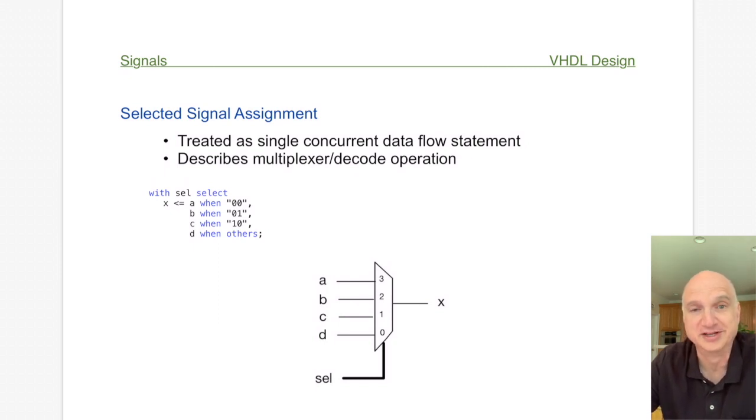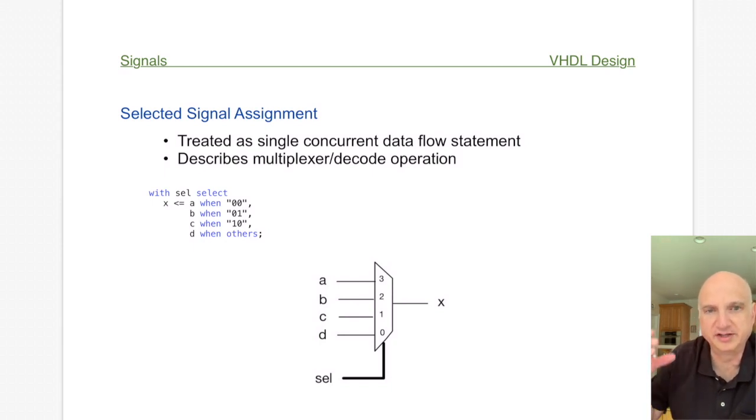But remember what we said before, it's really a bad idea to create a complex VHDL design in one giant process. That's asking for trouble and lots of debug time. It's much better to plan out your design, block out the functionality, figure out how you want it to work, and then declare the elements within it.